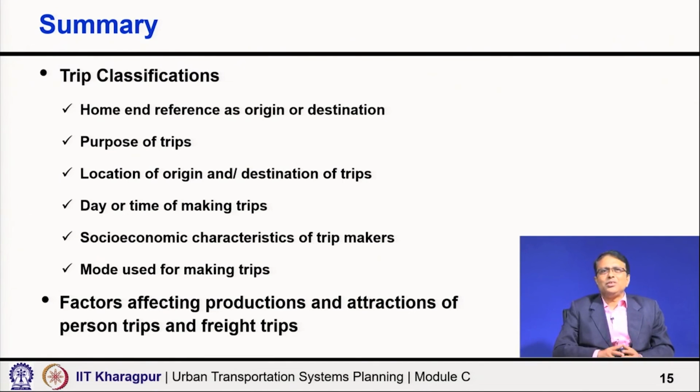So, day and time of making trips based on the socio-economic characteristics of the trip maker, high income, low income, and so on and so forth. There are different characteristics which are important. Then also looking at the trip based on mode used for trip makings, car trips, taxi trips, public transport trips, NMT, non-motorized transport trips. So, different mode wise we try to model the trip productions and attractions. That also is very interesting and may be meaningful in some cases.